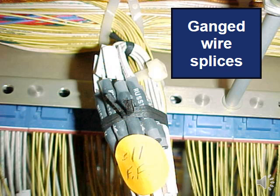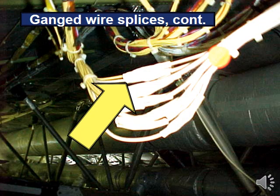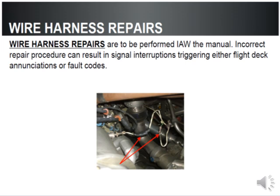Now here's an example of a bundle that looks like it has a tumor. All these splices are in the same place, so now the wire is bulging and it could cause potential installation problems. In this case, we have splices that were made with wires that are too short. Now we have mechanical strain. Now it's important to make sure that splices are done properly and in an airworthy method. For example, this looks like somebody used electrical tape around the splice. I don't think electrical tape is allowed.